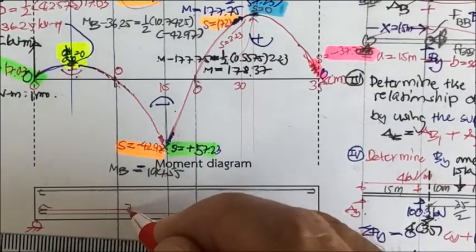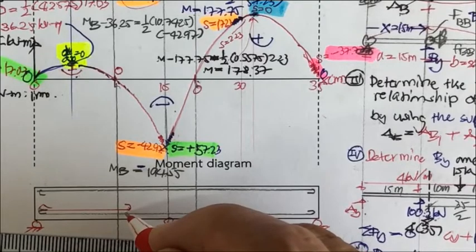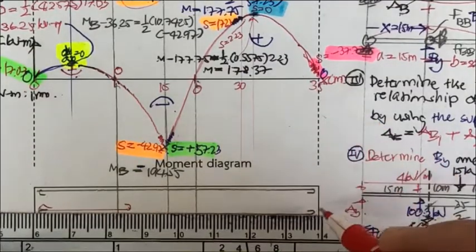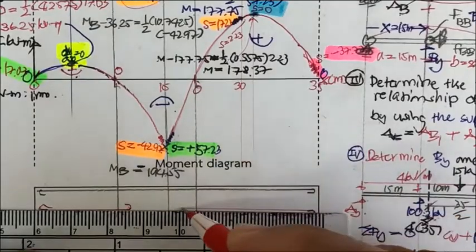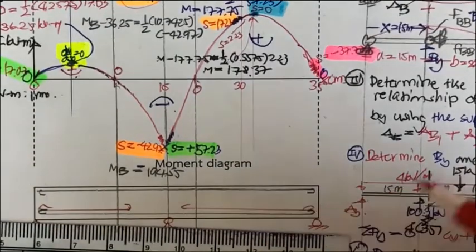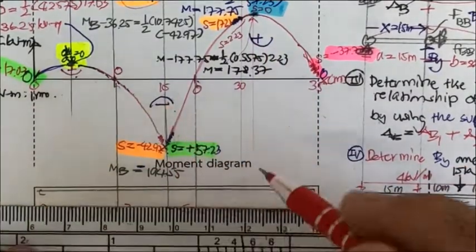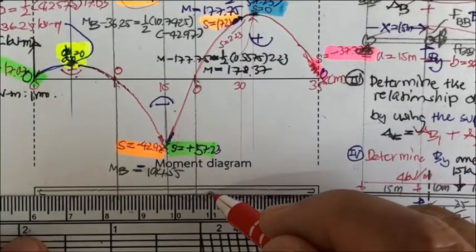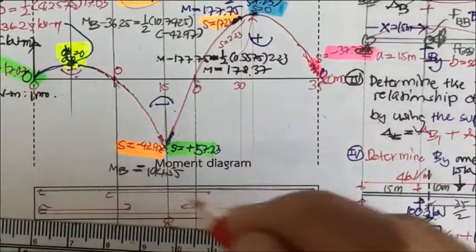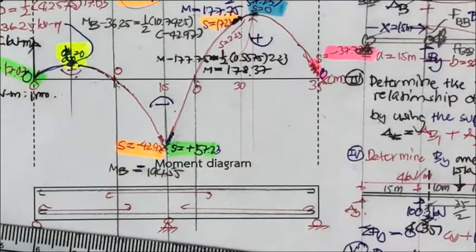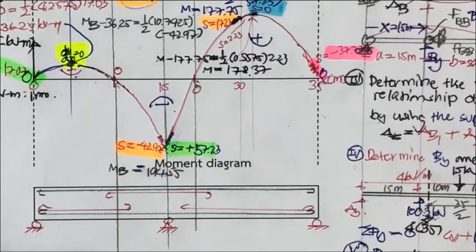Okay, don't forget to have some development length here. So the bond between the concrete and the steel will be fully bonded, and this also. Okay, this is for negative. For positive moment. For negative, you just put it on the top. Okay, that is the reinforcement for this.